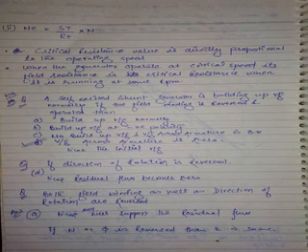If you increase the speed of operation of the generator above critical speed, what is happening to the RC value? Is it the same value or increasing? Increasing. If the machine is running at 1000, definitely it is more than that. If it is running at 1200, it is definitely more than that. So the critical resistance value is nothing but the shunt field resistance value when the machine is running at critical speed. As you operate above that, automatically critical resistance will increase. That is what you have written there. The critical resistance is directly proportional to the operating speed.